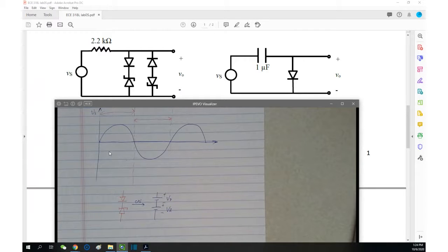Okay, this is the model of it. Does it make some sense? Be very careful of orientation here, okay? So you have a diode with the anode towards up and the cathode towards down, and the corresponding AC large signal model is like this, right? Positive polarity at the top, negative polarity on the bottom.